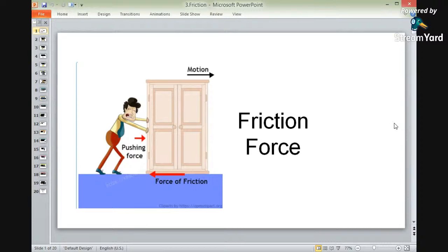We have applied the conditions for equilibrium as summation of Fx equals 0, summation of Fy equals 0, and summation of moment equals 0. With the help of that concept, we have solved problems related to forces applied on beams. Depending upon the different conditions, that is, whether there is a hinge support or a fixed support, we have solved the problems related to equilibrium.